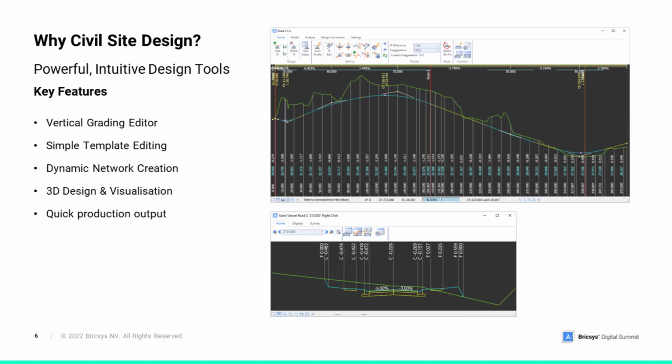The first one is the vertical grading editor. Now, just a quick mention about the fact that this is actually a separate form. Much of what you do within the software allows you to have separate forms that you can resize and move onto separate screens rather than all being muddled up inside the drawing environment. The great thing is the vertical grading editor allows you to edit the vertical geometry and profile of all of your strings within the project.